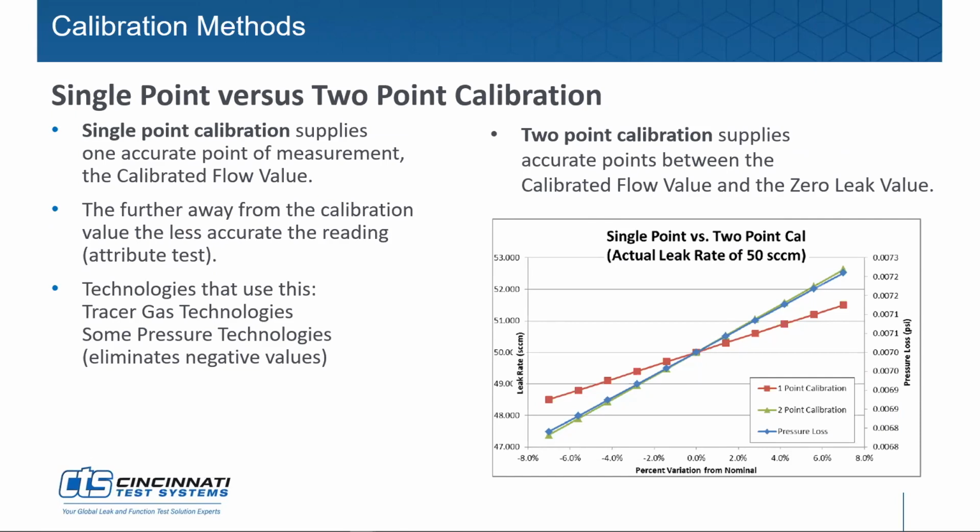So that gives you a good start, and then select a leak standard that's standardized so that you can correlate it to other tests. Remember, one of the biggest challenges, of course, is that just because it's leaking out of the part underwater doesn't mean it's going to leak out of the part when it's in operational conditions.